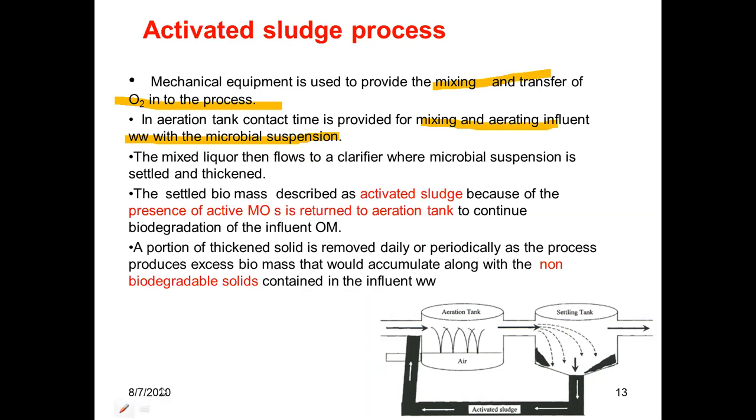Remember this term, mixed liquor. Mixed liquor of wastewater means the liquid or the water in the aeration tank. After mixing and aerating influent wastewater with the microbial suspension in the aeration tank, this mixed liquor is sent to the settling tank.